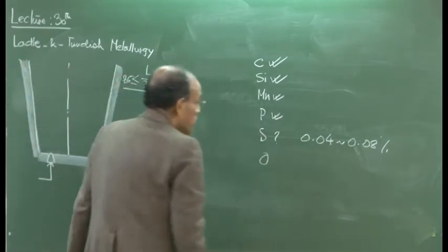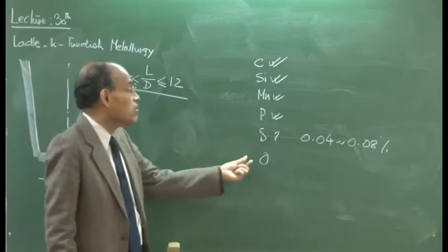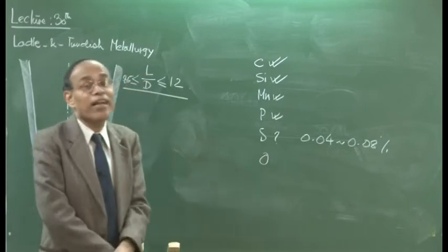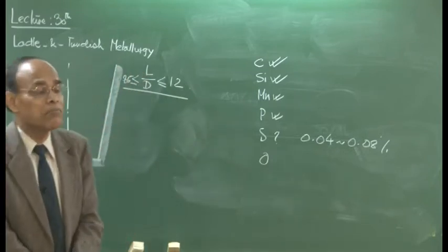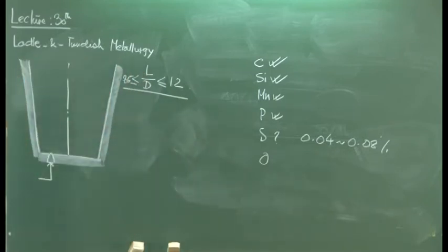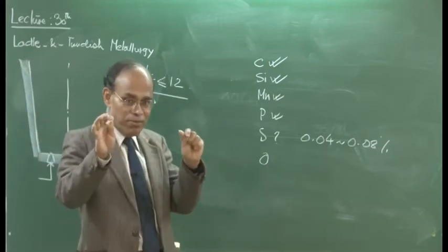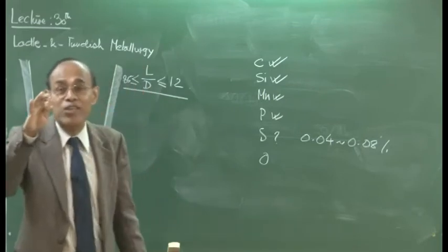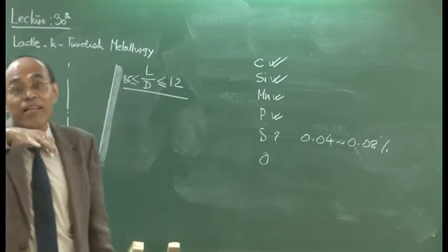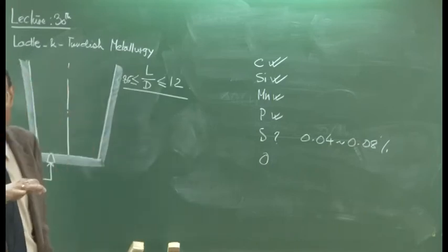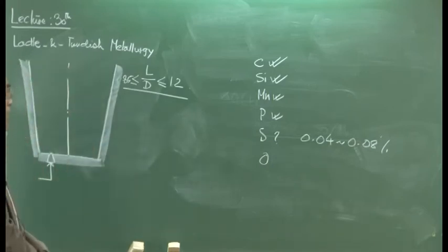and if you have carried out deoxidation, in that case we can understand that we have some dissolved element, dissolved silicon and aluminum, but nonetheless we have taken enough precaution to make sure that the deoxidation is carried out in such a way that the residual content of silicon and aluminum are not above the threshold desired by the customer.